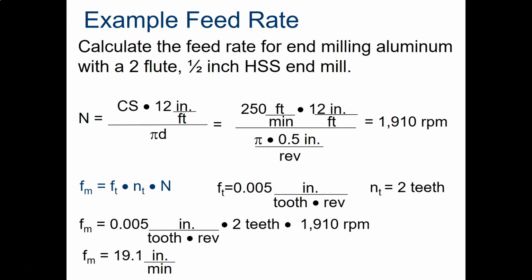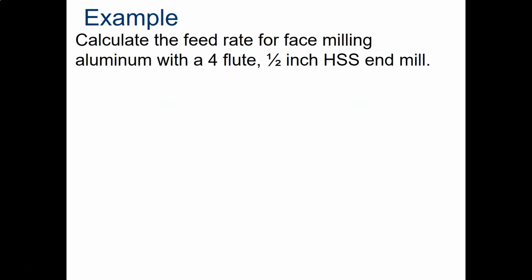Now that isn't very fast when you consider that we can move through machinable wax at around 3,000 or 4,000 RPMs and near 40 inches a minute. Our mill can speed up to 10,000 RPMs and move at around 100 inches per minute maximum. Our CNC routers can engage material at 18,000 RPMs and feed through the material very quickly as well. But we're dealing with a metal, with aluminum, and that metal is more dense than something like wax. Okay, let's do another one.